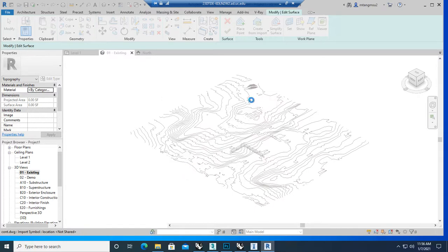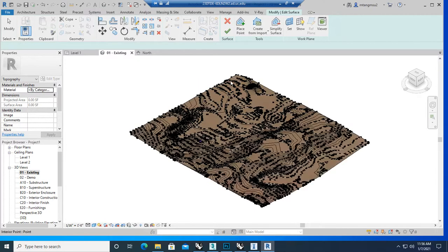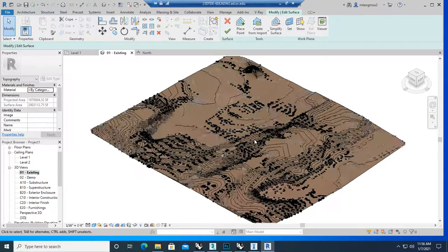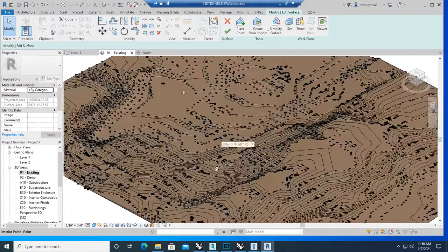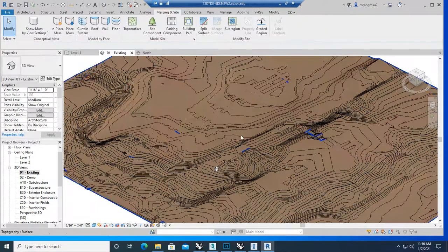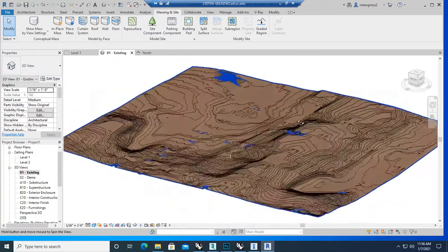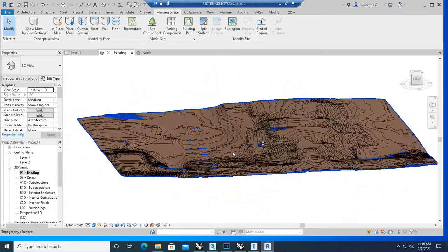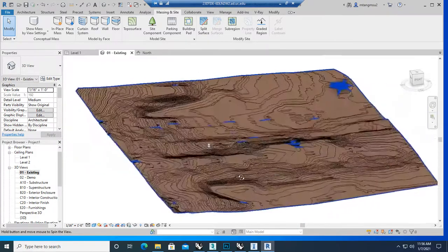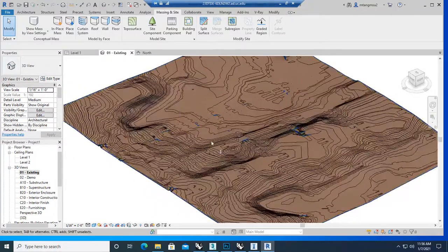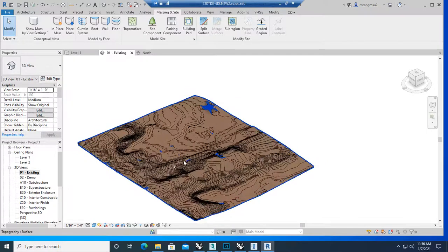But if you just click OK, it should pick up all the geometry from that layer and automatically generate the contour lines, all the Topo Surface. Click OK, then you have this really nice, clean Topo Surface, right? So this is the whole process of how you can start your own topo. If you don't have anything given to you, you can start from scratch.